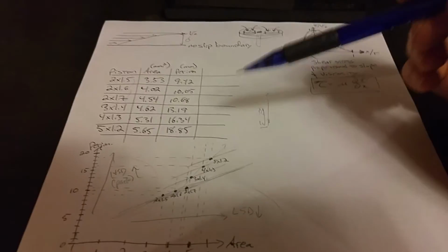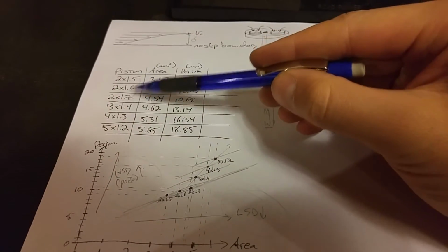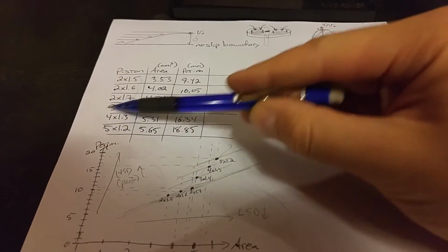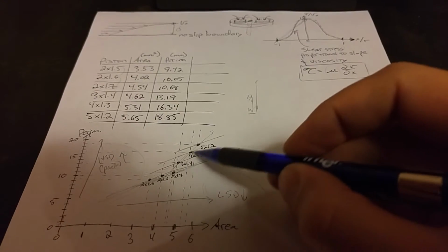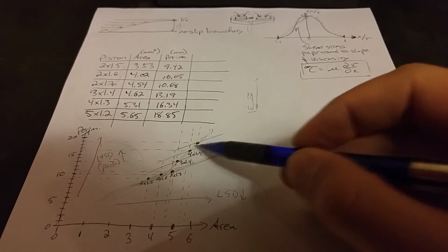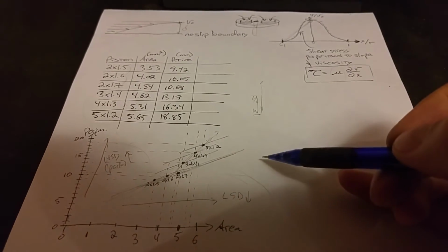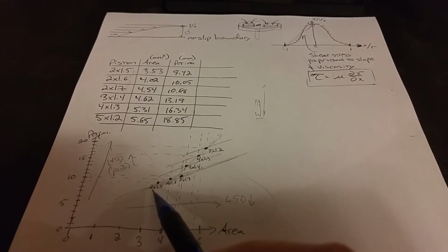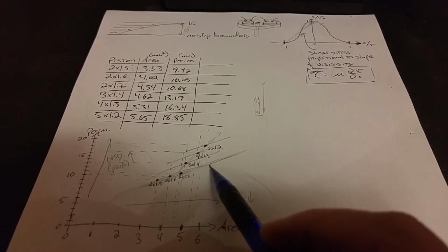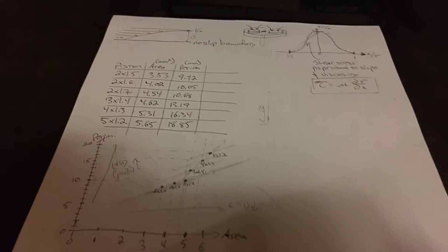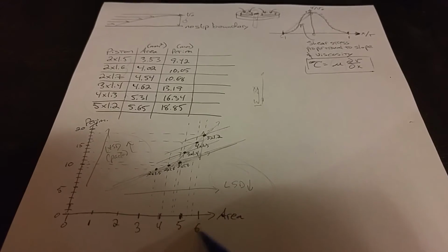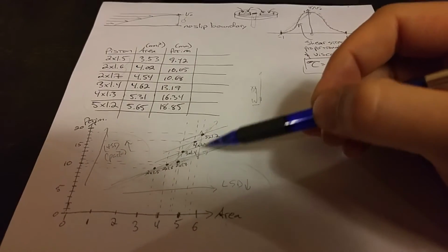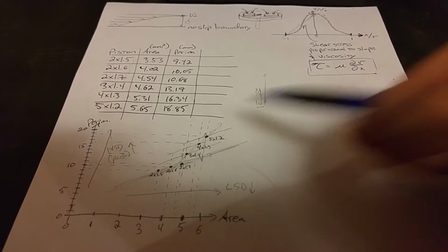So I can do that by going toward a larger number of piston holes in my shock piston menu here. That will move me along this curve here. I can get quite a lot more pack with a 3, 4, or 5-hole piston than I ever could by just taking a 2-hole piston and increasing the piston size. So for the same amount of low speed damping, I can achieve higher pack with more piston holes.